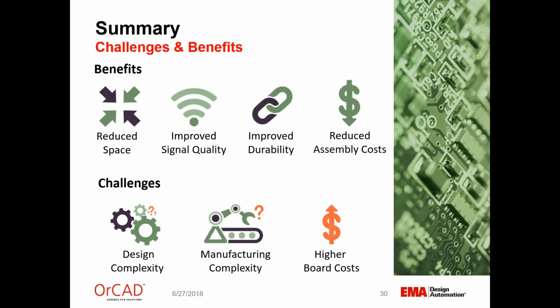So just to summarize, the benefits of flex and rigid flex design are reduced space, improved signal quality, improved durability, and reduced assembly costs. The main challenges are increased design complexity, increased manufacturing complexity, and higher initial board costs.